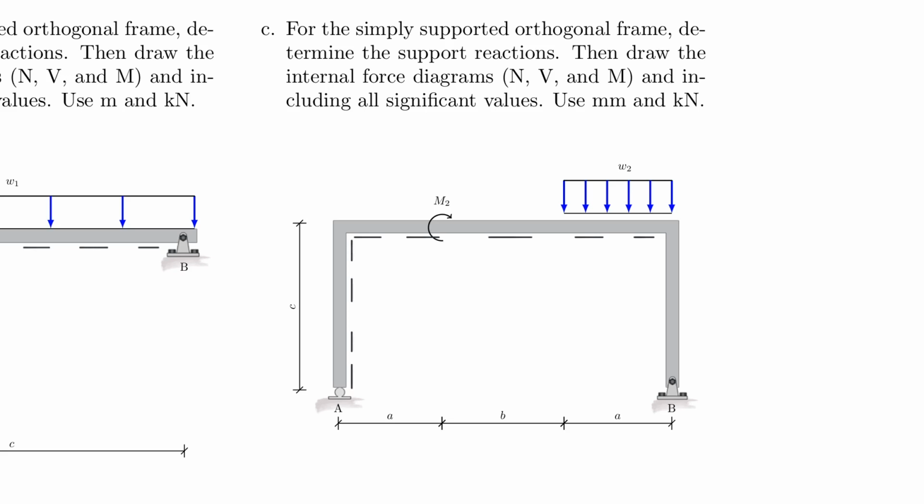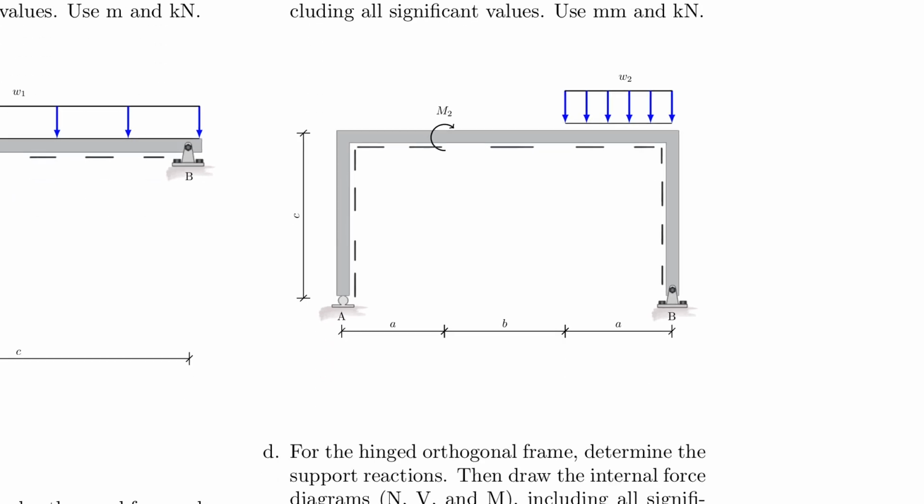However, the internal forces, they are slightly different than they were before in a beam, but I think the lecture provides you all the knowledge you need to solve this problem. Just understand that, again, this is an easy problem compared to the lecture that we've done or the example problem that we've done, because it's not a hinged frame. It's just a simply supported frame, as you can see here. So I have a roller, not a pin and a pin. If I had a pin here, I needed a hinge somewhere. In fact, that is what we see in our next problem.